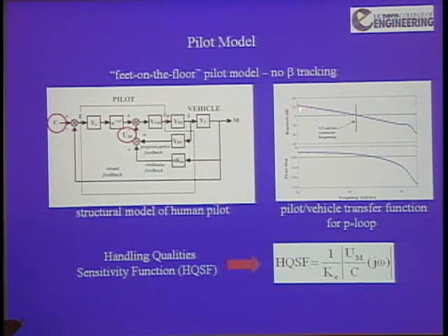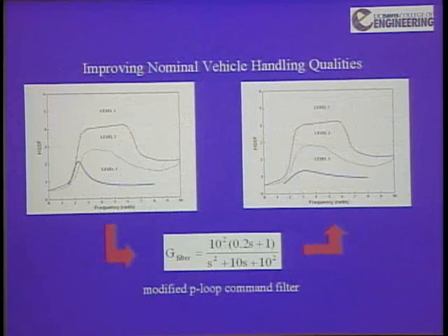We're going to give you a series of roll commands, the pilot model. Here is the open loop transmission with the pilot model in the vehicle, 20 dB per decade, 1.5 radian crossover frequency. Okay, so what we did then is say, what's the handling qualities at the nominal condition, low and slow. And what we found out was we're in level 2.